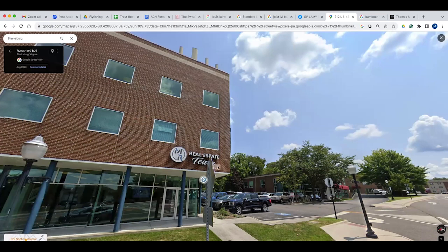Now what was an issue was that this is a big dead load. Masonry is heavy. Once again, this corner can't deflect, because if it deflects, this masonry starts to open up and crack. If this bends down, I had to specify rigid connections at all the beams and column connections, so that all segments of the W shapes in back of here, supporting the roof and floors, every segment of it, all the flanges and the webs, are continuous.